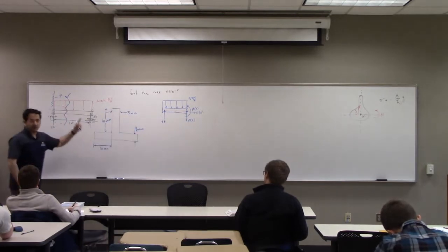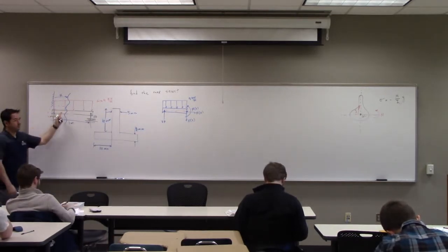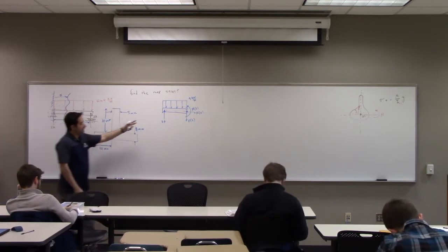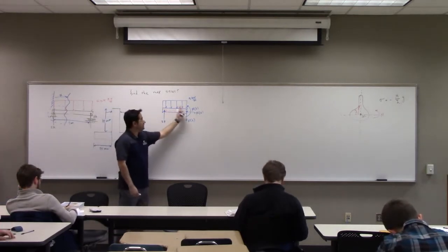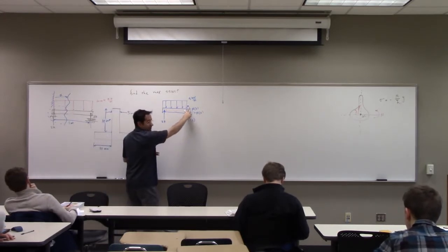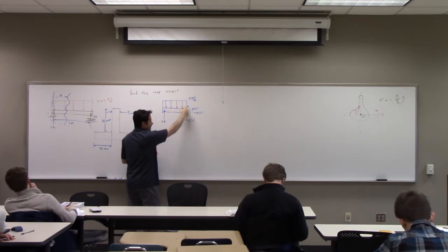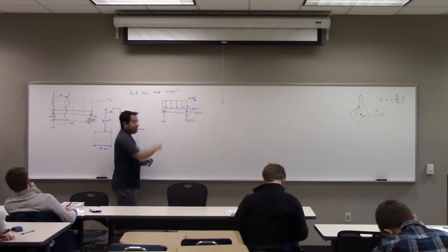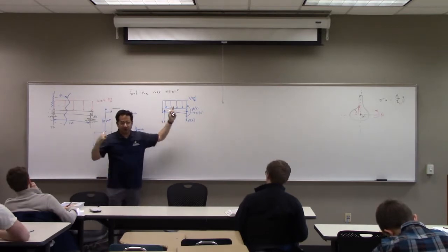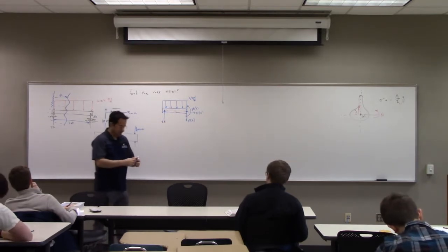So when you cut the beam, also draw the part of the distributed load. Now, in this FBD, the distributed load is kind of an external load, but I include the internal load in this part of the system. Now, can I replace it with a point load? After you cut it, then yes, you can replace it with a point load.